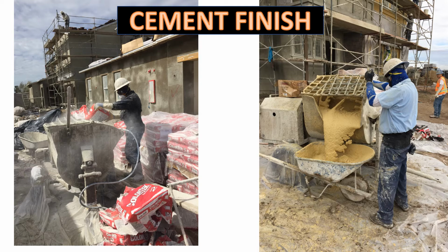Cement finish coats are the oldest of the stucco finishes. At one time, the term stucco referred only to the thin finish coat and not the whole assembly. Blending your own cement finish is possible but unadvised, particularly for integrally colored cement finish coats. Pre-blended products have greater workability and improved consistency of texture and color. A pre-blended cement finish has the precise mixture of sand, cement, and additives. All you need to add is potable water.